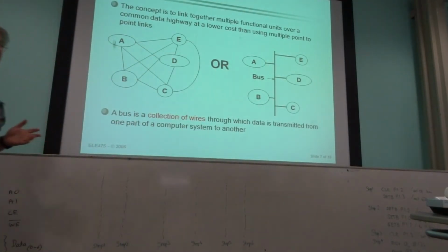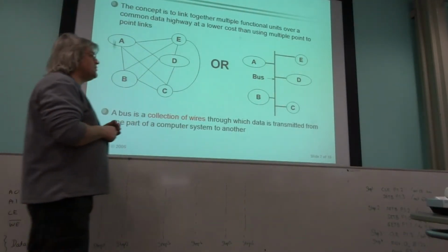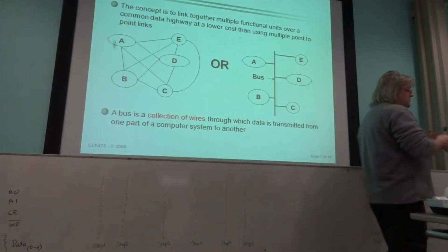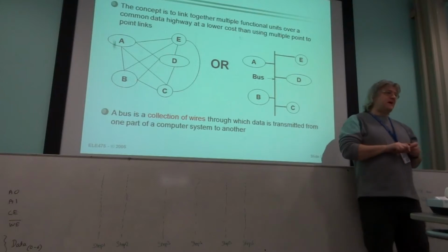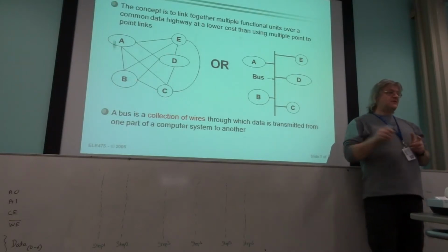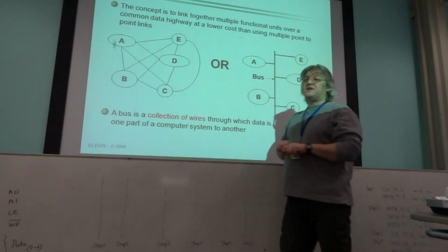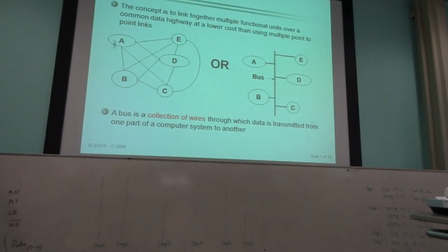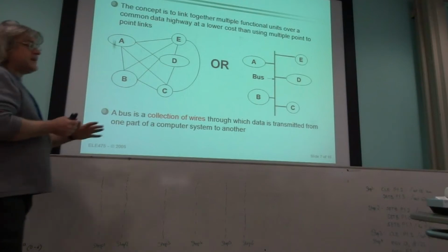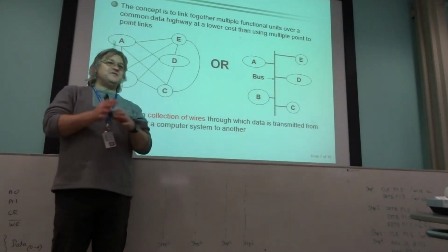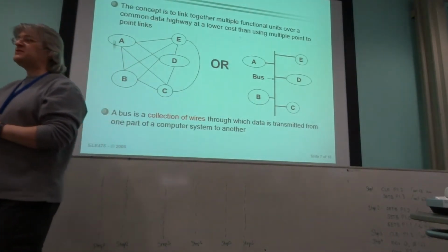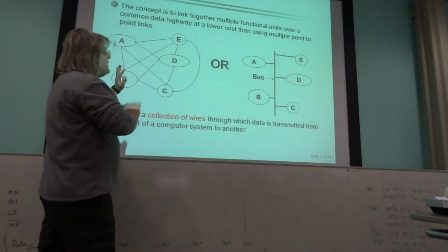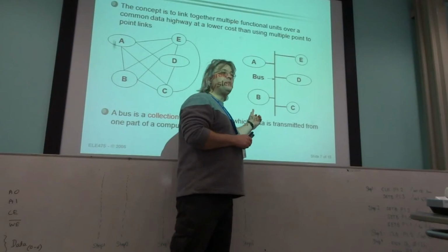There are devices out there, quite a lot of them that we use, where, for example, the maximum speed at which they can operate is about 2 megahertz. But the microprocessors that we're using may well go beyond 20 megahertz. So even if you get the sequence right, if it tries to do these transitions too quickly, it might be too fast for the peripheral that you're talking to. Okay, enough nagging about that, let's move on.